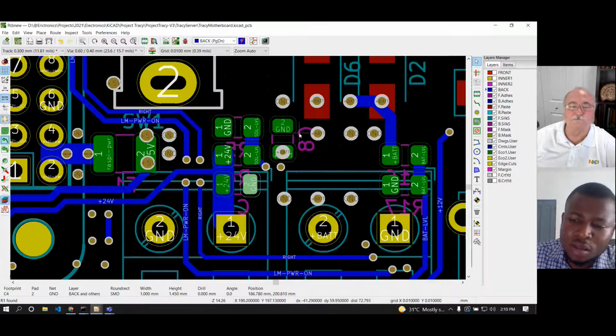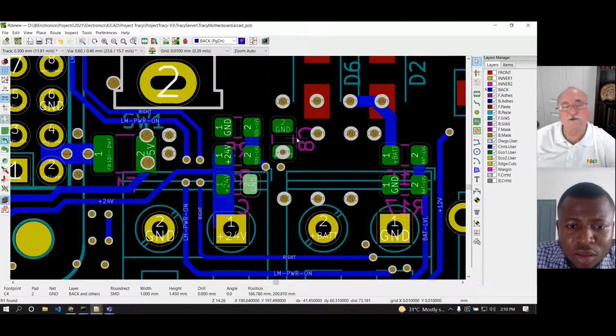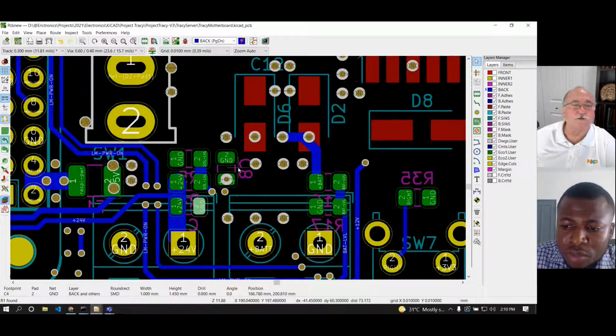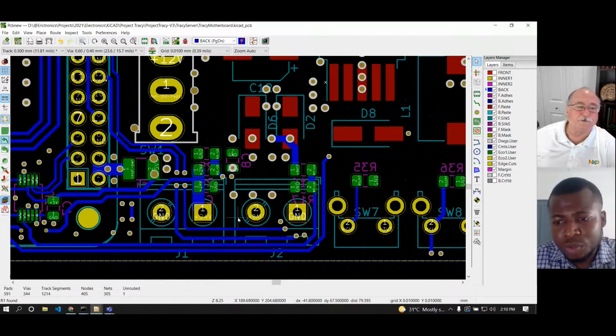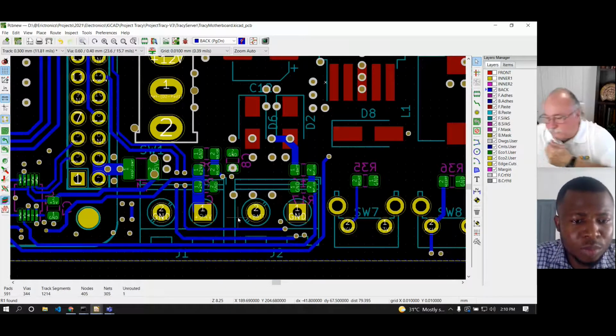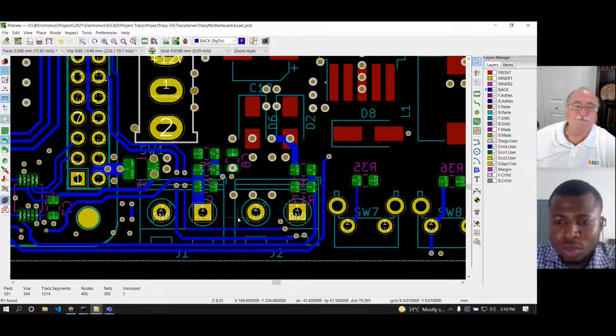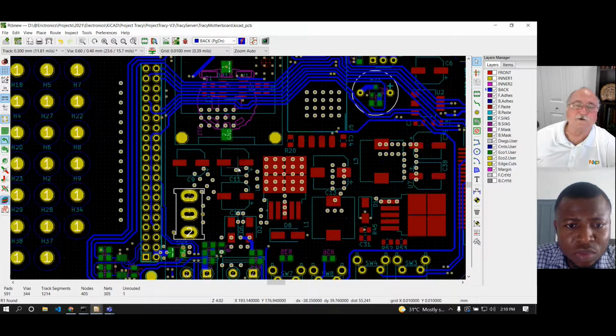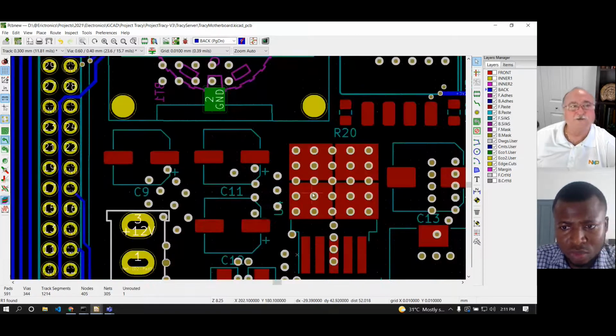I guess the first one on battery needs to be small because its job is to catch noise on the power supply, on the wire. Okay. And we did the same thing for the input from the solar charger. And then once you get to the bigger capacitors, that's where the energy is stored coming from the wire harness to the big capacitors. And then their job then is to supply the energy to the voltage regulators.